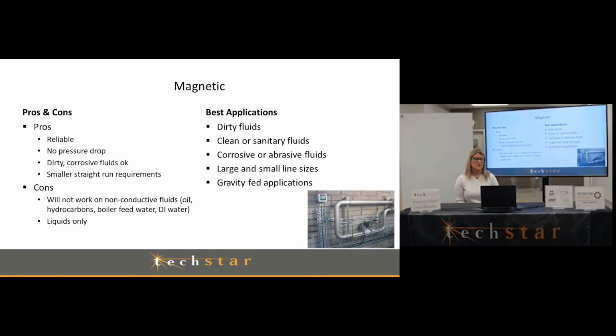Pros and cons. Pros are really reliable. They've been in use for a very long time. Once again, there's no pressure drop. They can handle dirty, corrosive fluids. The nice thing about mag meters is that they have liners. So you can specify the liner based upon your fluid type.